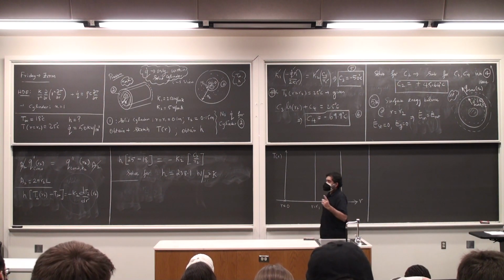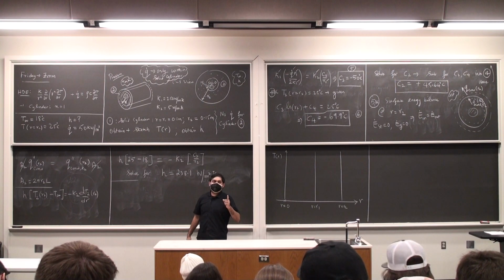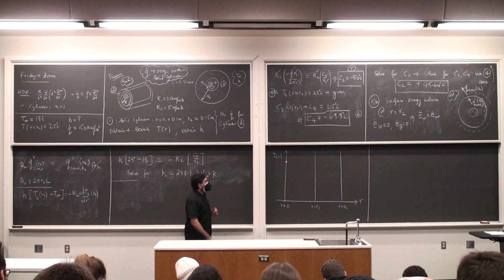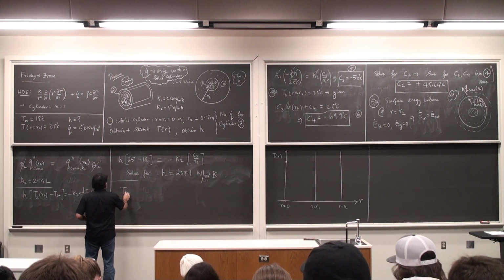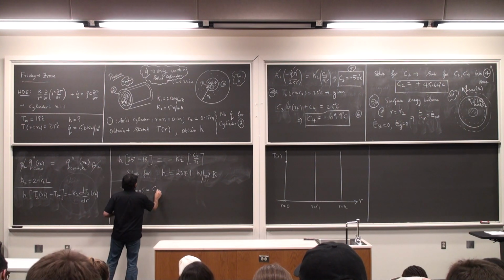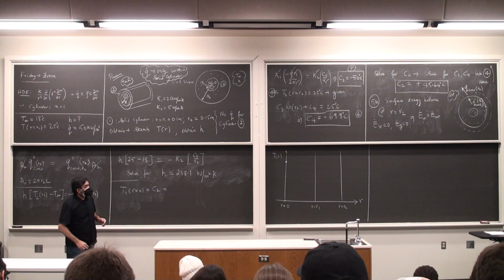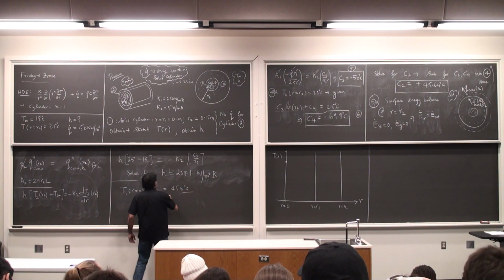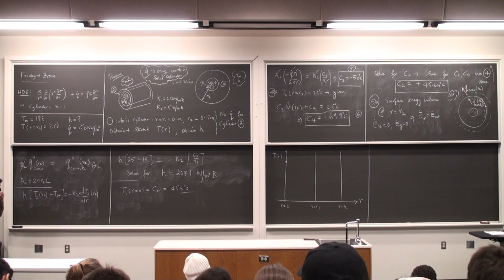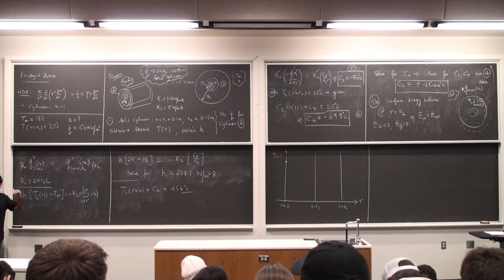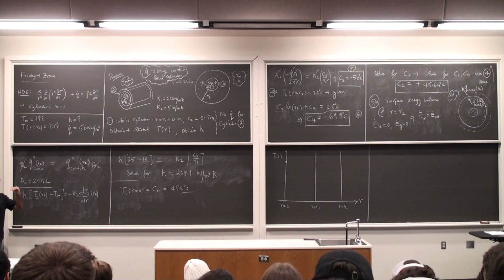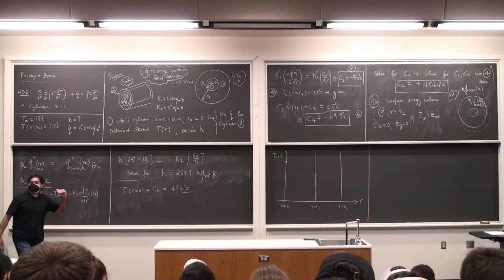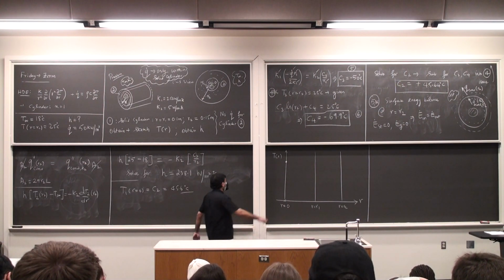Temperature at R equals 0 is the highest, so that's going to be the highest point in my curve. Okay? So this is obvious here. If you want, you can do the substitutions. T1 at R equals 0 is essentially C2, which is something that we calculated, 45.6 something. How do I start off at R equals 0? What's the slope? It has to be 0 because the center line is insulated. We just came up with that first boundary condition. So my slope is 0 here.